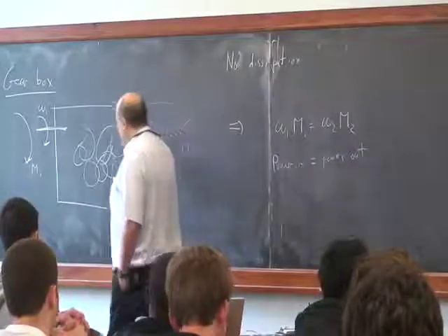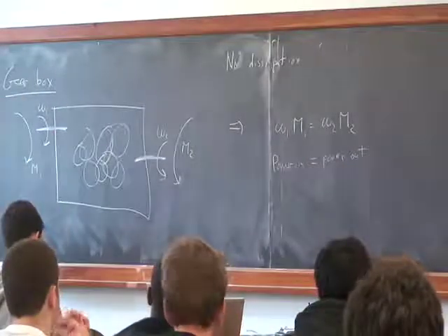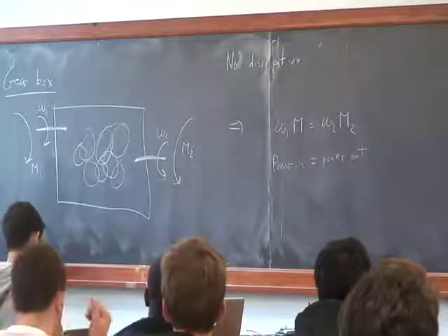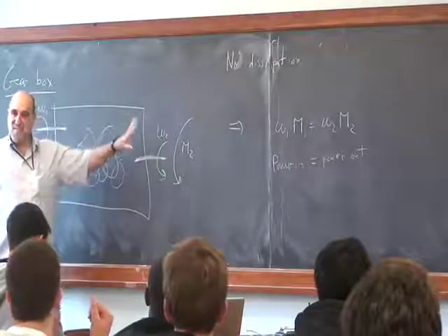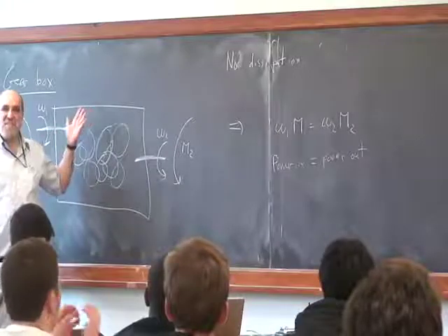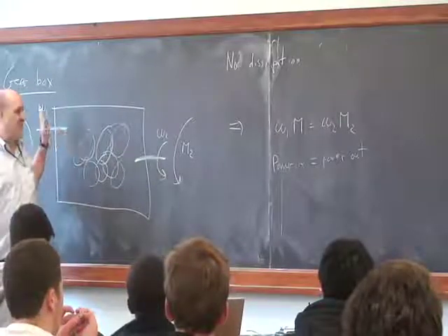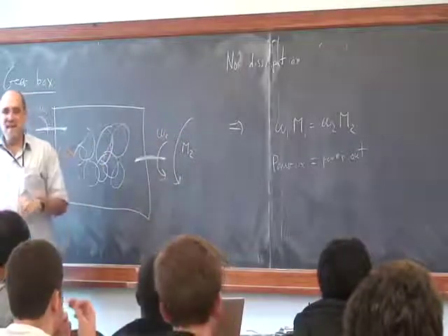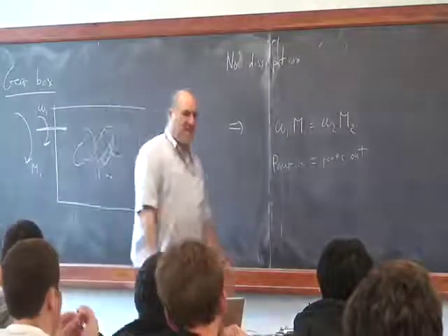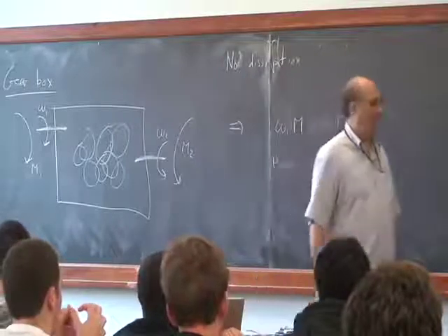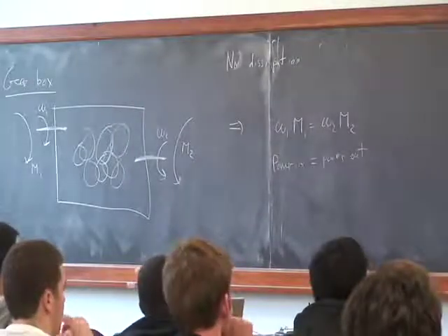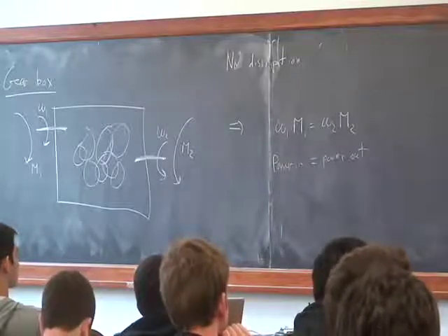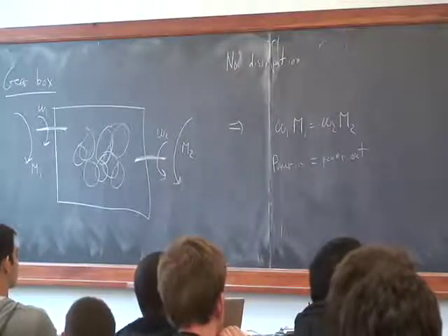So when you make a machine with a motor, you can think of the gearbox as this thing which approximately conserves energy. Maybe it loses a little bit. Of course, all things conserve energy, but it conserves mechanical energy, that the work in is equal to the work out, or maybe you get a little less out. And this is true for bicycle transmissions and car transmissions and little electric motor transmissions and so on. Now, how much do you really lose in a real gearbox? It's a property of the gearbox.